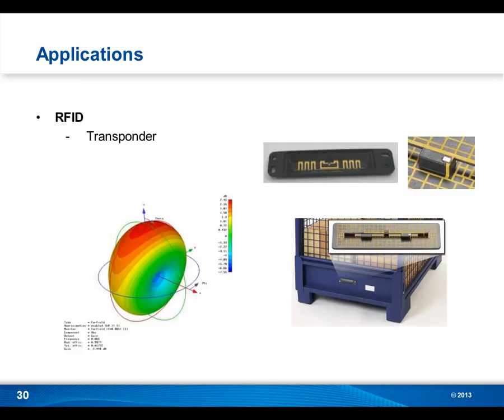So this next application you're looking at is this rugged RFID transponder. Don, talk to us a little bit about this application. Well, as Shane pointed out, this is an RFID transponder. It's a good fit for LDS because it necessitates both long paths, both conductive and inductive paths within the part.